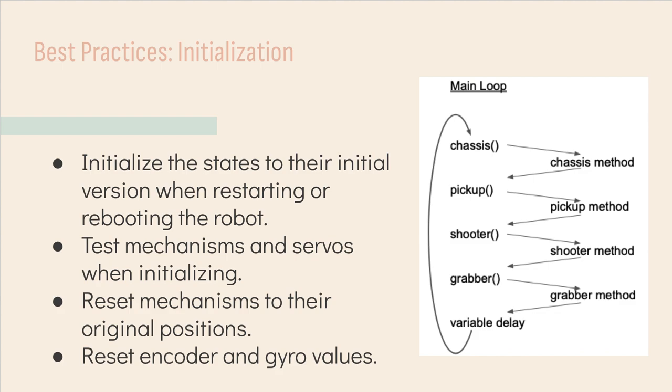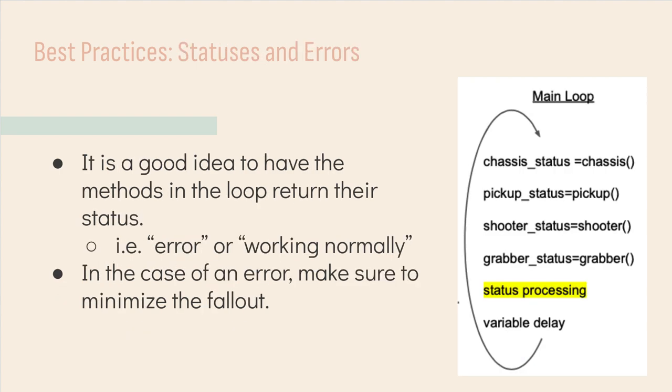Initialize the states to their initial versions when restarting or rebooting the robot. Test mechanisms and servos when initializing. Reset mechanisms to their original positions. And reset encoder and gyro values.